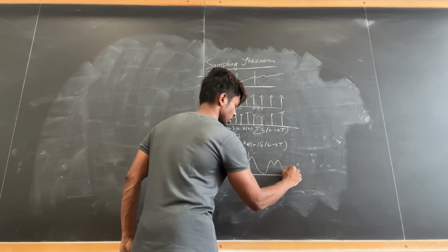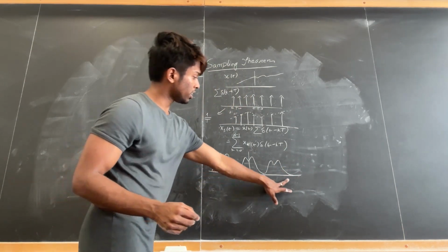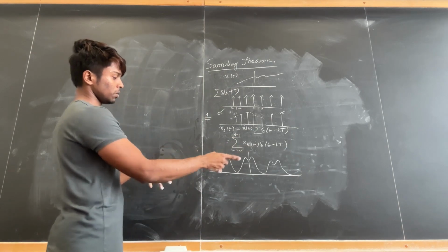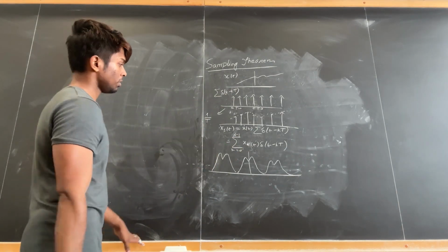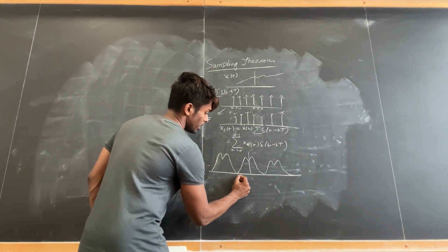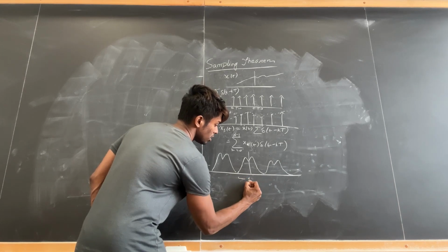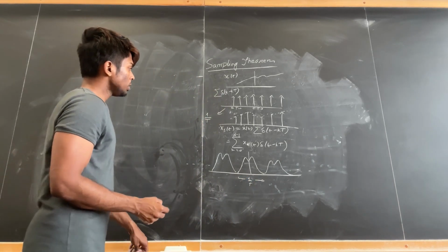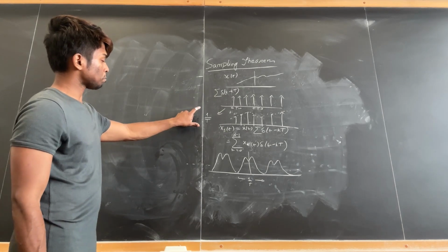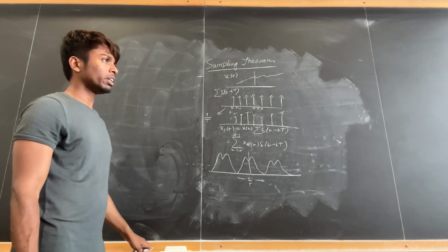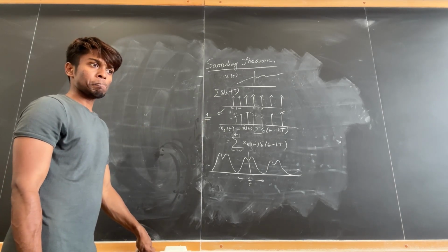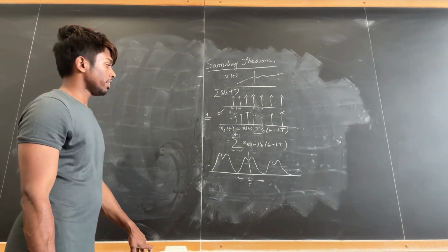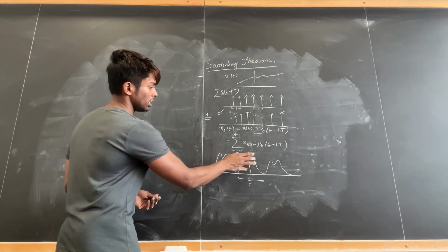Now if this periodization happens, these are in certain periods. What is the period of this particular response? After how much time does this repeat? After a period of 1 by T, this periodization keeps repeating. Now if the sampling is done at a frequency which is greater than the highest frequency component, then the copies will be far from each other.